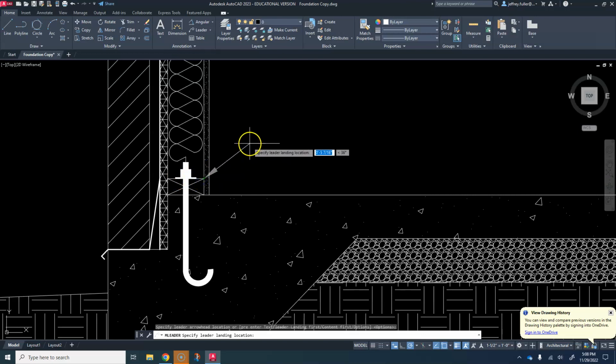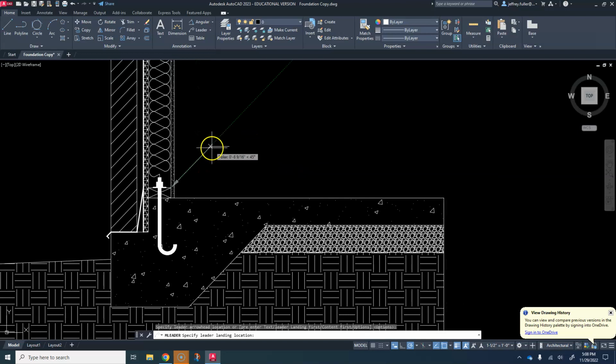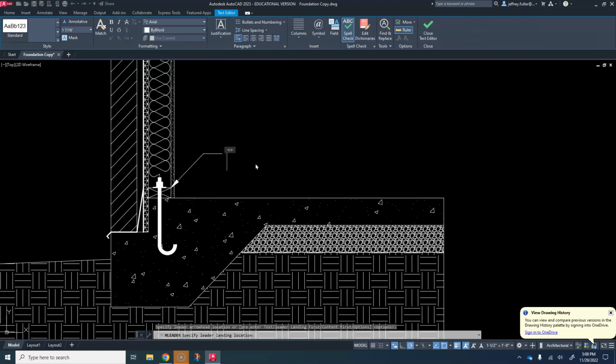It's going to form at the end. See that arrow? And then I'm going to draw it out to about right here. No specific distance, just draw it out to about right there. I'm going to click, and then that establishes my text box where I can type in the stuff to describe this stuff down here. So make sure all caps is on. So turn on all caps.